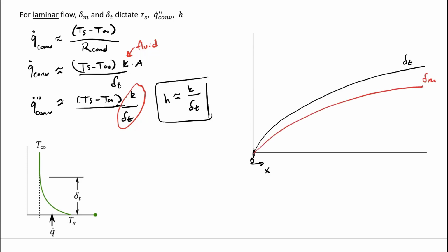Delta sub m. Just to pick something. Okay, so let's sketch out what we think the heat transfer coefficient H is going to look like. I'll draw this in green. So what is my H going to look like? If I plot H as a function of position, what is H going to be at 0? Infinity, right? Right at the leading edge, there's effectively an infinite heat transfer coefficient, meaning my surface temperature is exactly equal to my free stream temperature.